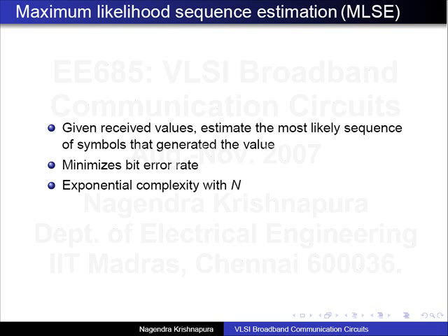So you basically trace the path of the signal, and n symbols can contribute to the received signal at any given point. And given the received value, you can figure out what path it took. That is, you decide the path it took with the highest probability. So that way you minimize the bit error rate. That's what you should do. But the problem with this is if the channel impulse response is long, the complexity of this procedure is too much. You just cannot do it.